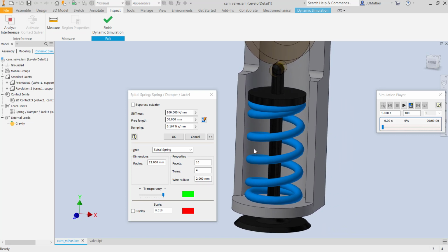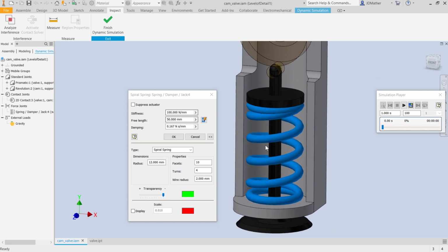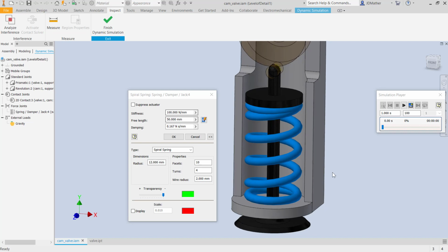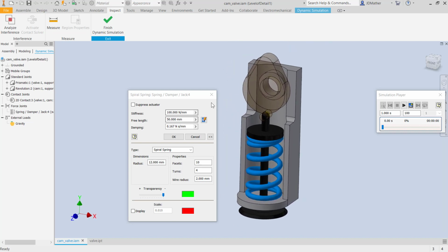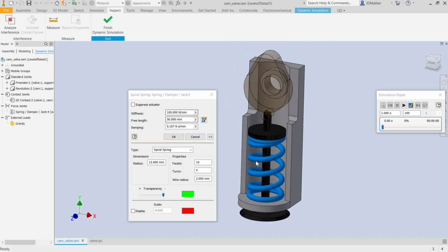In the real world, if you ever do a valve job on a car and you go to take the springs off of the valves, there'll actually be an outer spring and an inner spring, and you have to use a special tool in order to be able to remove those springs, because they're incredibly strong springs. They're really stiff springs. So when you see information about what percentage of energy from a gallon of gasoline actually makes it to the axle, one of the losses is in compressing these springs. It takes a tremendous amount of force to keep that spring, or keep this valve against the cam.